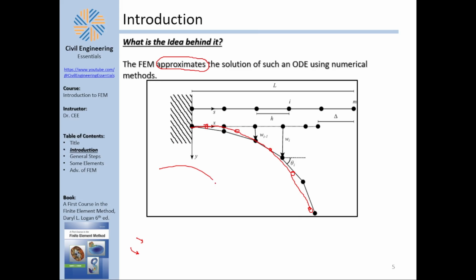Allow me to explain. If you have a parabola like this, if you are using 2 points like this, then there is a big margin of error between what your approximation is, that's your approximation, and what the real deal is. Now, if you use 3 points to approximate the parabola, 1, 2, 3, then you can see that the margin of error is decreasing. The area that seems to be the error is smaller when compared to this one because you have more elements. Now, of course, if you discretize more elements, you would get a better accuracy. So you would think, wait a minute, this means I can make my elements really small.